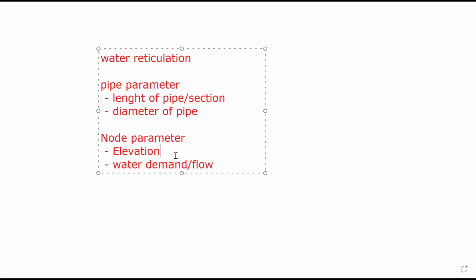Okay, so two things the surveyor does for you, but it looks like one thing. He does elevation, takes the spot height, uses GPS and gets the height. When he now goes to his office, he plots it. And you, being an AutoCAD expert, being an engineer, can now measure point A to point B, measure it out and get the sections. With the length and the sections, you can establish two parameters, leaving you with two more parameters. The two next parameters are what you, the engineer, will determine.